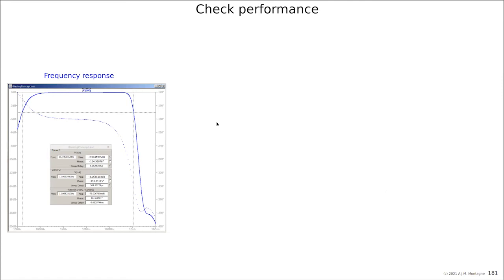I think everything was done in LT-SPICE. The results will be a little bit different if you adjust all the widths, because there was a little bit of attenuation in the current mirror because the ratios weren't correct. But okay, let's say we have no showstopper because everything works.